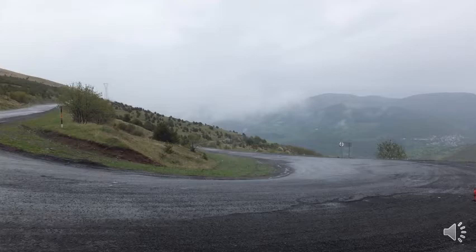It happens there and not on the straight parts of the road, because on these corners, that's where cars are braking, and that's creating a shear force. And so that road is wearing away. It doesn't have enough durability because it didn't have enough shear strength.